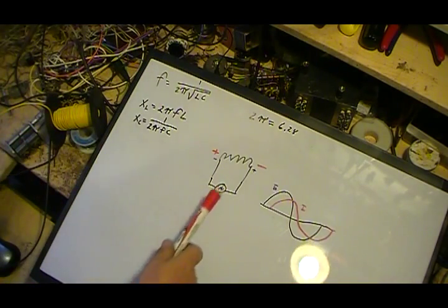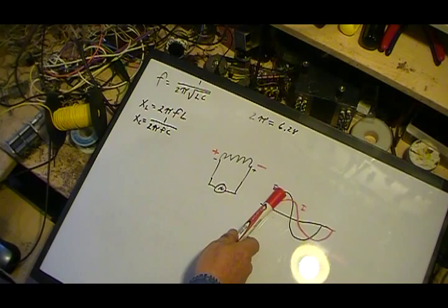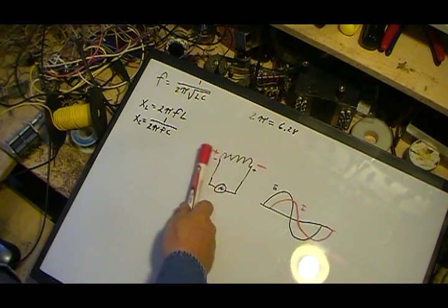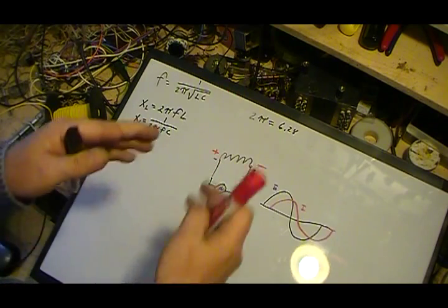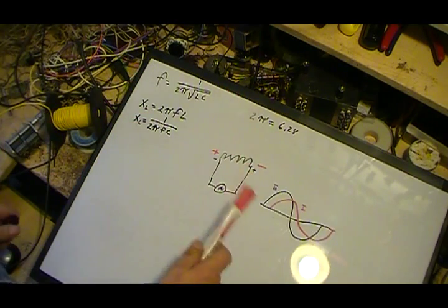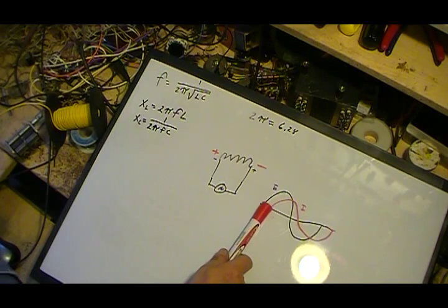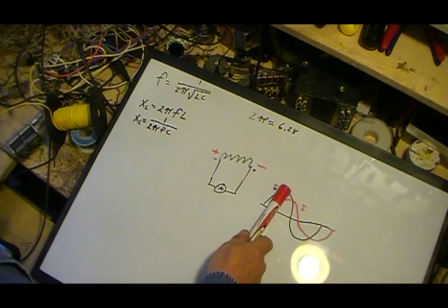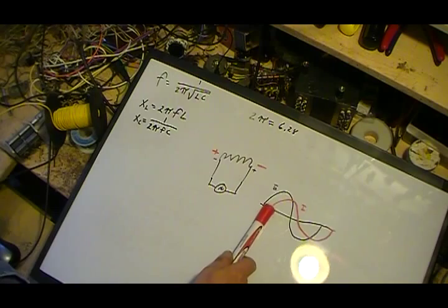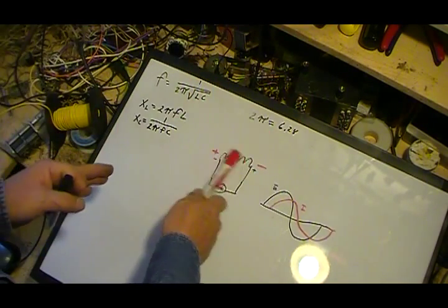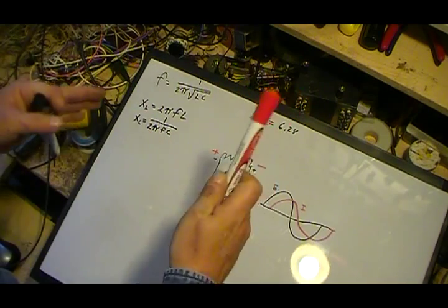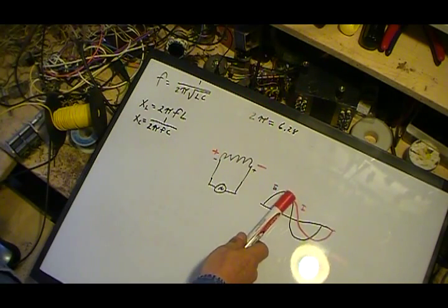What happens is the voltage starts building first, but with this counter EMF in there, the current can't flow because it's canceling itself out. The current doesn't start flowing until approximately 90 degrees later. Then it'll start flowing, and that's generally about the time that the EMF or the voltage is at max. At that point, because when it hits max, it stops moving. The field stops moving. Everything stops moving. Now the current can start flowing.